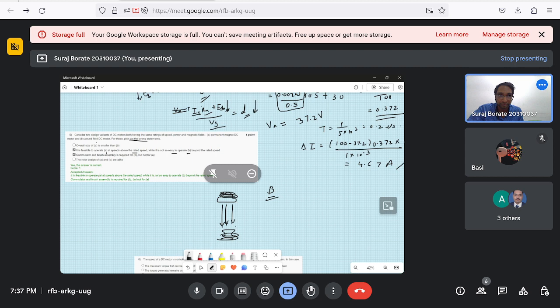Yes, sir. So T on should increase. If T increases, T on should increase, but that doesn't mean VA should be affected, because VG is constant. So VA will be constant, because D is constant. So the average value of the voltage remains constant.